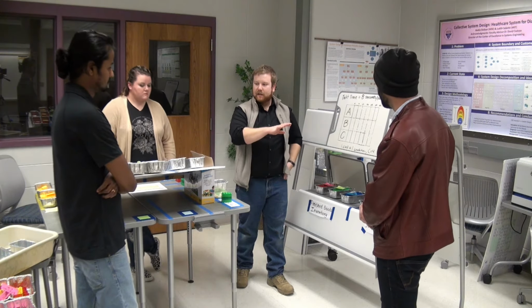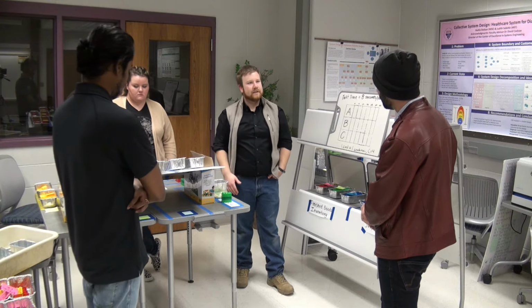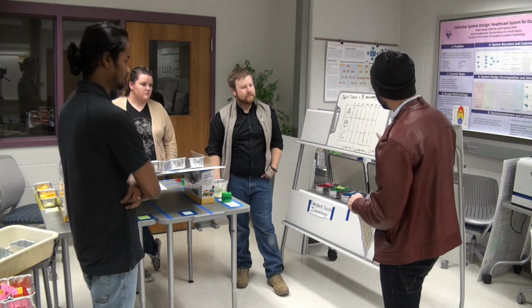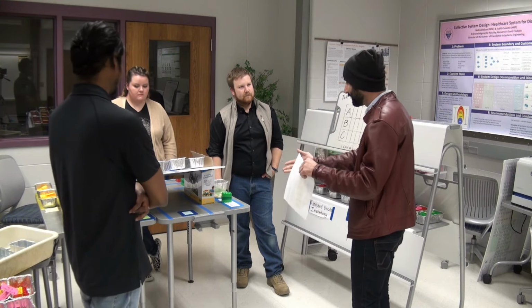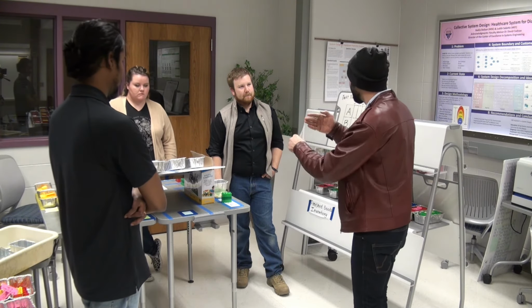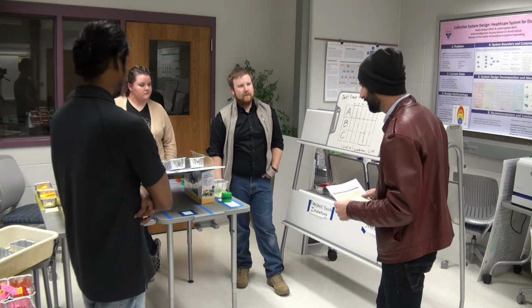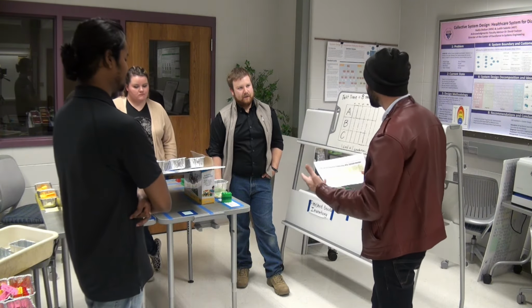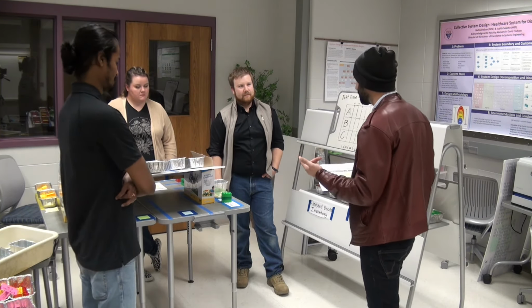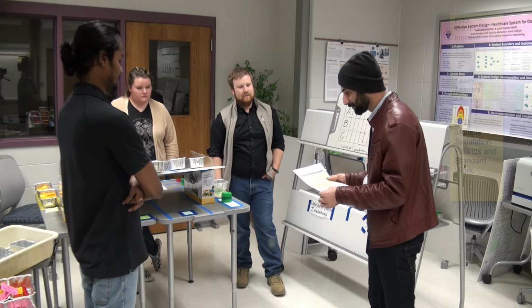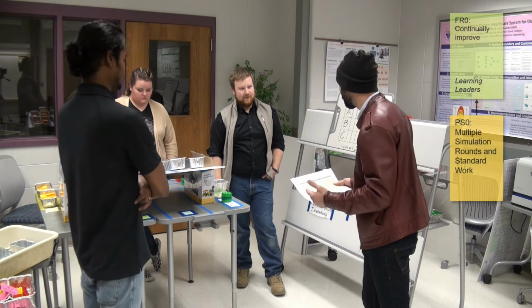We were able to level the demand on the whole system this time. So if you notice, we leveled the demand, we reduced run size, and we also reduced the unnecessary inventory, as they go hand in hand with each other. I see it more like continuous improvement, the physical solution of the very first initial effort that we have, which is to continually improve throughout the process.